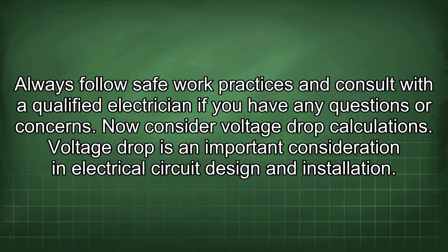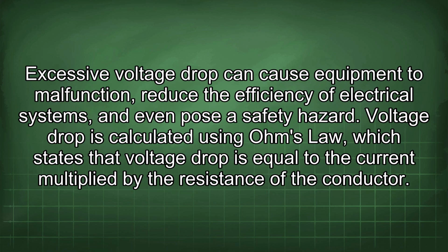Now consider voltage drop calculations. Voltage drop is an important consideration in electrical circuit design and installation. Excessive voltage drop can cause equipment to malfunction, reduce the efficiency of electrical systems, and even pose a safety hazard. Voltage drop is calculated using Ohm's law, which states that voltage drop is equal to the current multiplied by the resistance of the conductor.